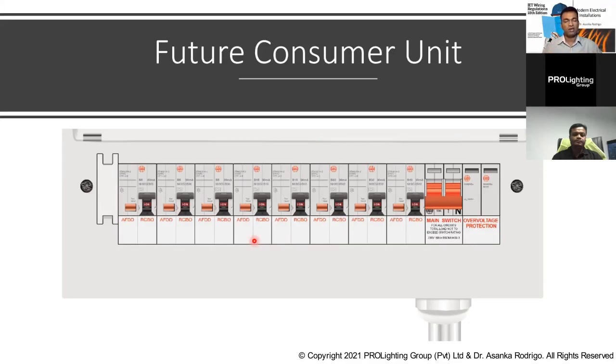Especially with arc faults, people experience many fire hazards in modern buildings, where even a minor arc fault can propagate and create a fire hazard. Because of that, arc fault detection is very important nowadays, especially in apartment buildings, hospitals and schools, locations where there are higher risks. You have to have arc fault detection in those types of locations.